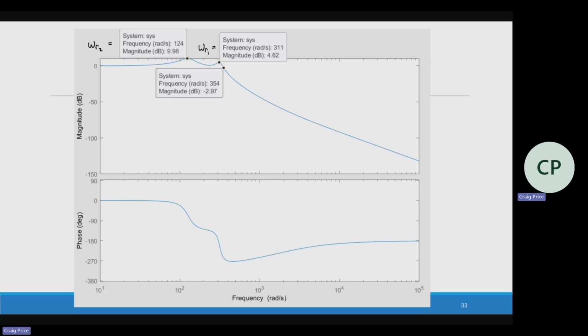So if this was a different kind of system where I had some kind of sinusoidal input, I could be looking at, how do I avoid those resonant frequencies? I might not want to be at really low frequencies because I still get some amplitude, but if I can have an input frequency that's a lot higher, I might not see any transmission.